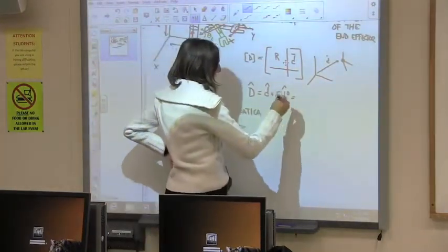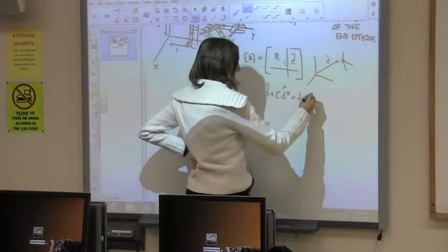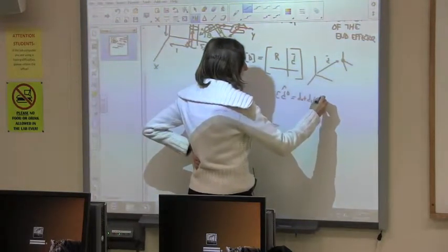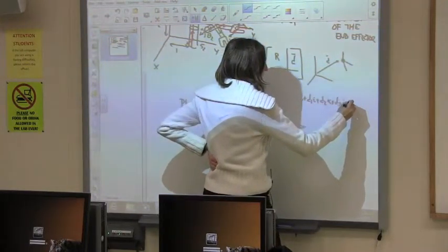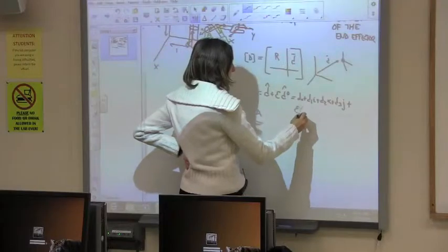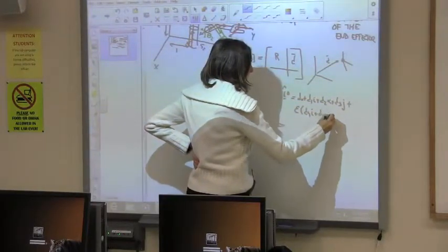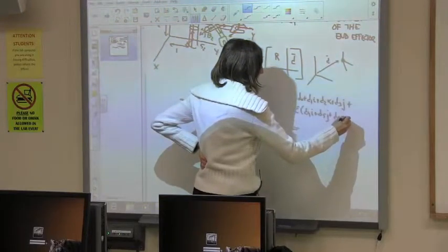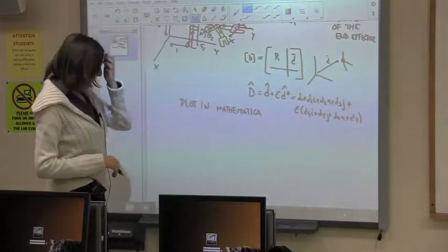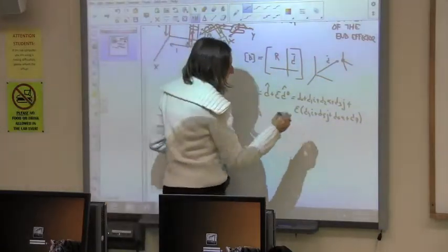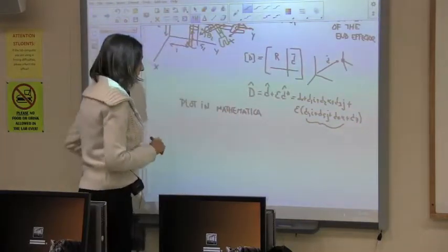Let me just put, so this will be d0 plus d1i plus d2k plus d3j, remember all the components, plus epsilon, d4i plus d5j plus d6k plus d7. These are the 8 components of the dual quaternion, right? So what I want to take is this vector in quotes, okay? This dual part of the vector.